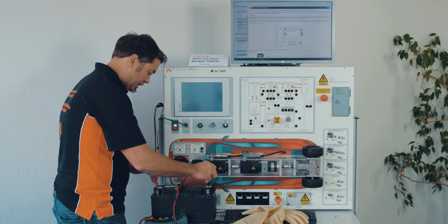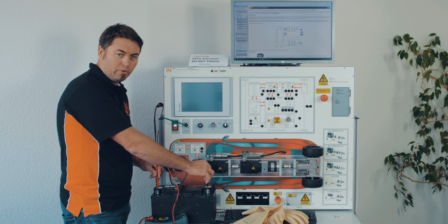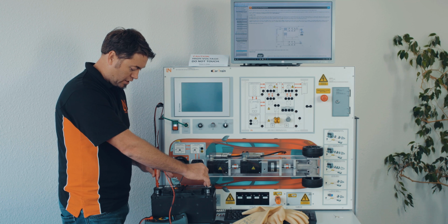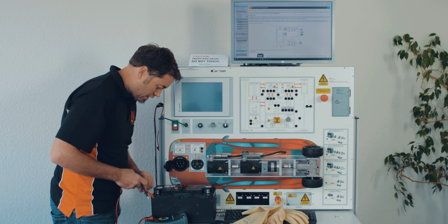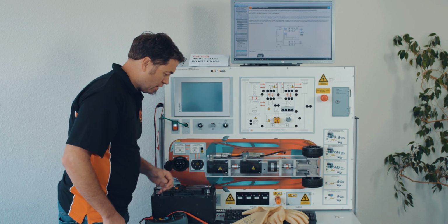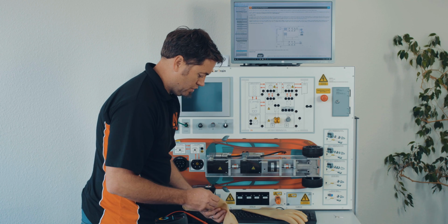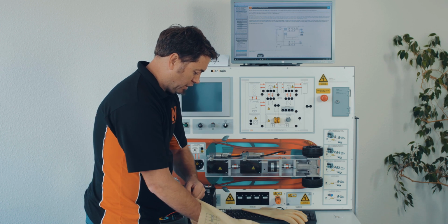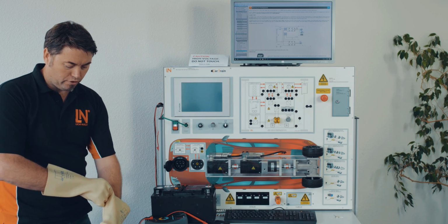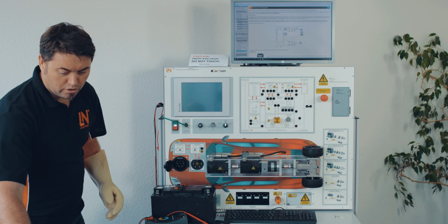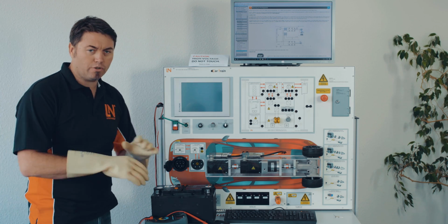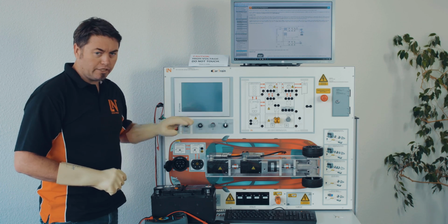So the very first thing we need to do is test with a real battery. We want to check the same type of voltage. Here we're using DC. We'll be testing DC high voltage, but at least we're testing DC here. So I've got a 12-volt battery, and that's shown up, works good. Okay? I've tested my gloves, put them on. If we've got leather over gloves, put those on as well. Unfortunately, these are too small for my hands, but you get the idea, we put them on. We've taken the ignition key out.